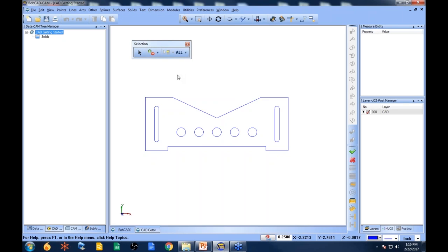There is a selection function here. There's a toolbar dedicated to selection. There's a black arrow. When you put yourself in selection, you'll see the button is depressed and your mouse pointer changes. It goes from just a white pointer to a white and gray pointer that is slightly larger. So that's how you know you're in and out of selection, okay? You can put yourself in selection by clicking on selection. You can get yourself out of selection by escaping.